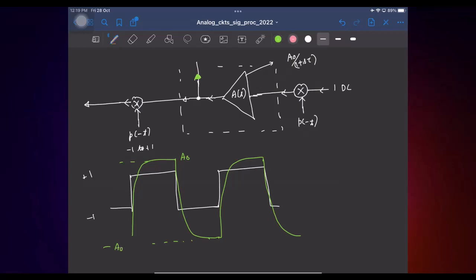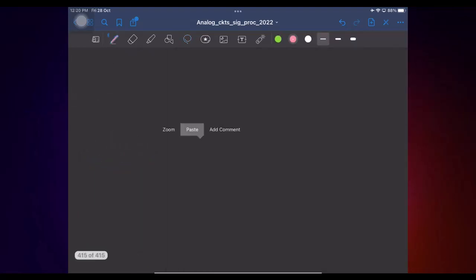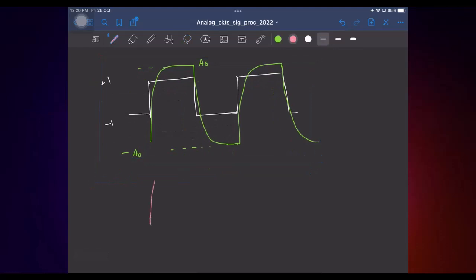So what about the signal that comes here? I mean this signal is basically tapped here and the same signal flows here, right? And this gets multiplied by this square wave. So what happens? Whatever was in the negative side, that gets flipped. So I'll have to probably take it to the next page. I'll have something like this, right? We saw that earlier also.